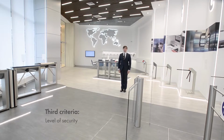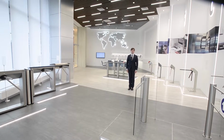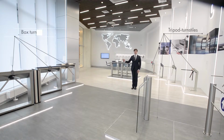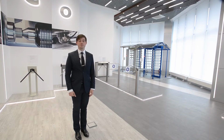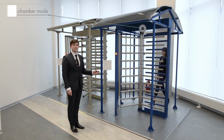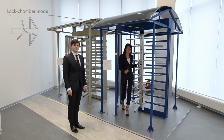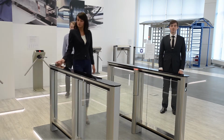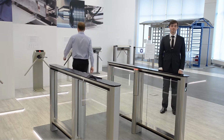Next selection criteria: providing correct level of security. In most cases, it is enough to install waist-height turnstile. Tripods, box turnstiles, speed gates, but sensitive facilities require increased security. That can be achieved with full-height turnstiles. They not only fully block the passage, but can also work in lock chamber mode. Installation of a canopy will protect from climbing over the turnstile. All turnstiles must give access privileges for one person, not allowing passing one after another using one ID card.